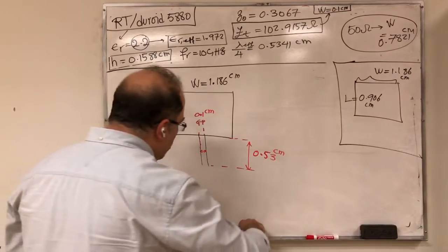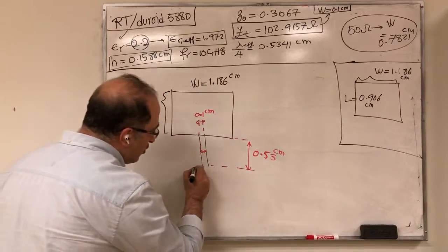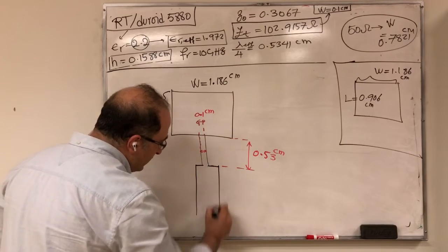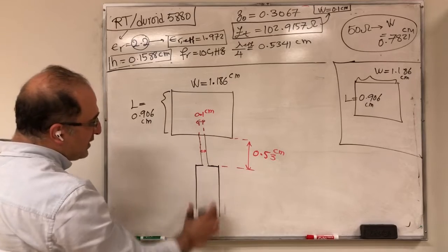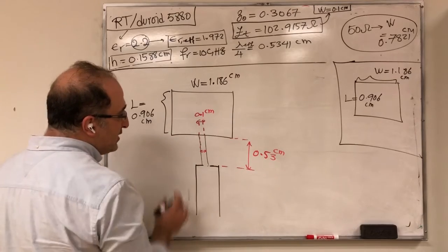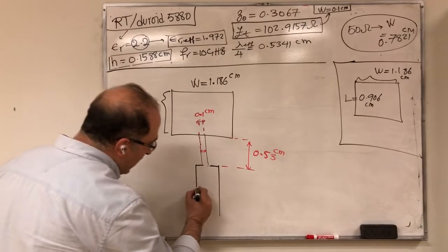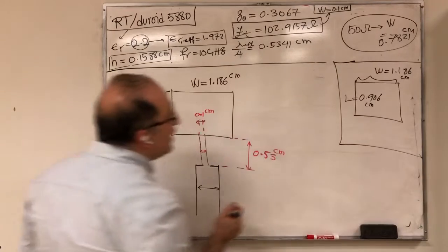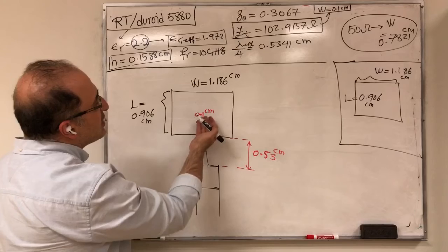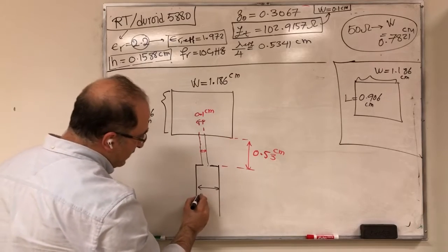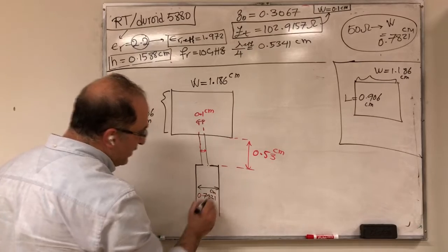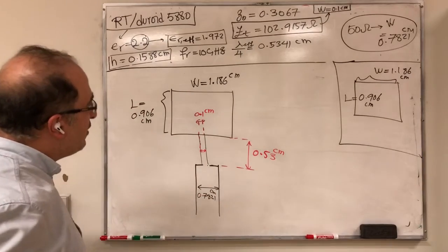And then we go to our 50 ohm. So the 50 ohm becomes wider, of course. And then the length is not relevant in this case for us. This was sensitive to be quarter wavelengths. And this width here would be 0.7821. So it's almost 7 times bigger than this, 0.7821 centimeter. So that becomes our 50 ohm line.